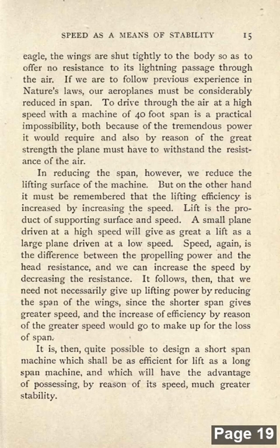In reducing the span, however, we reduce the lifting surface of the machine. But on the other hand, it must be remembered that the lifting efficiency is increased by increasing the speed. Lift is the product of supporting surface and speed. A small plane driven at a high speed will give as great a lift as a large plane driven at a low speed. Speed, again, is the difference between the propelling power and head resistance, and we can increase the speed by decreasing the resistance. It follows, then, that we need not necessarily give up lifting power by reducing the span of the wings, since the shorter span gives greater speed, and the increased efficiency by reason of the greater speed would go to make up for the loss of span.